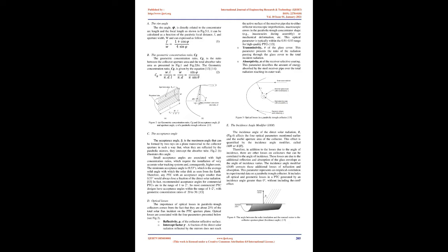Commercial PTC designs for solar thermal power plants are generally 100 m to 150 m long and have a parabola width of about 6 m, while PTC designs for industrial heat use are remarkably smaller. Parabolic trough collectors require solar tracking systems to modify their position with the changing apparent sun position in the sky from sunrise to sunset. Movement of this type of solar collector has only 1 degree of freedom, on-axis rotation. The most important PTC parameters are the geometric concentration ratio, acceptance angle, rim angle, and peak optical efficiency. The following paragraphs explain these parameters and others.